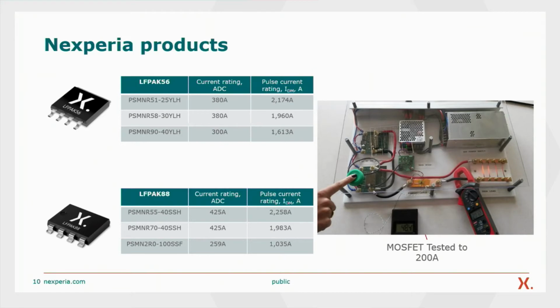This is a DC current. We've not done anything special. We don't press that button which sets off a chain of pulses. This is a DC current. And when we demonstrate this kit, we show that when you turn off the MOSFET, all of the inductance within those circuits and those load wires would cause the avalanche of the MOSFET.